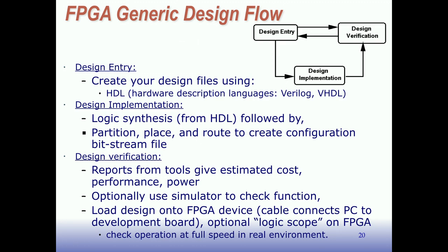You enter your design somehow. Usually these days you create your design using Verilog or VHDL, some other hardware description language. Then the design is implemented. A logic synthesis tool takes the HDL, parses it, and turns it into a gate-level representation. That gate-level representation, a large netlist, gets partitioned, placed, and routed. Partitioning is the process of cutting it up into smaller pieces or subfunctions. Placement figures out where each of those goes on the chip. Routing plans the connection routes between the various logic blocks. Then the tool can create a bitstream, which will program the device to implement the results from partitioning, placing, and routing.